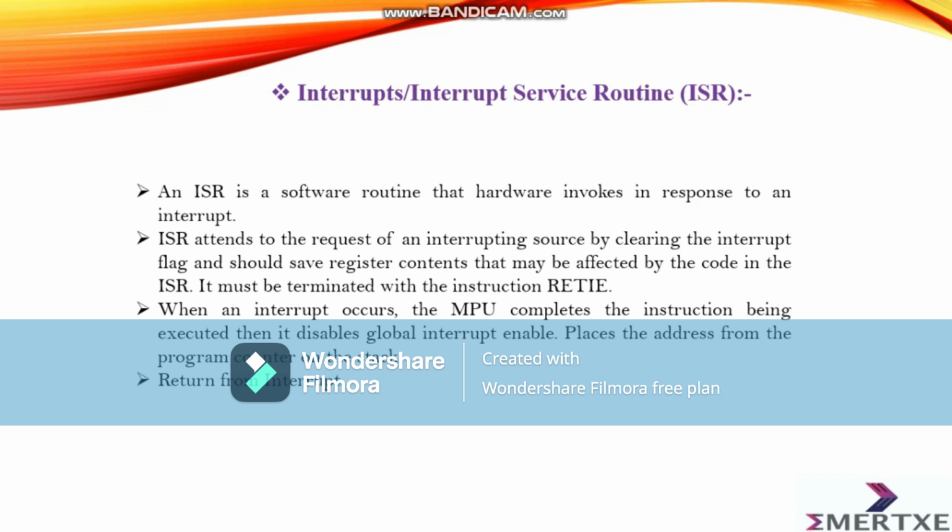When an interrupt occurs, the MPU completes the instruction being executed, then disables global interrupt enable, and places the address from the program counter on the stack, returning from the interrupt.